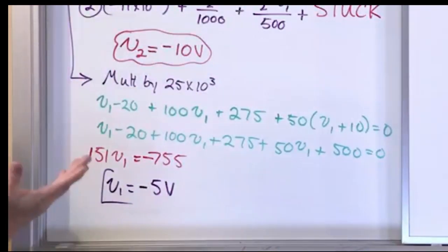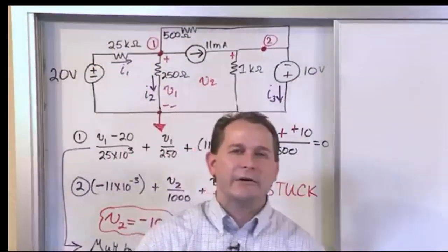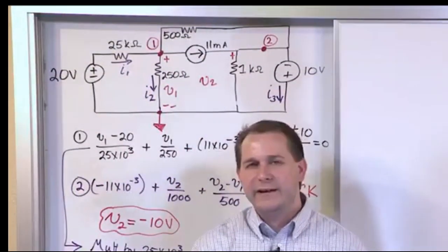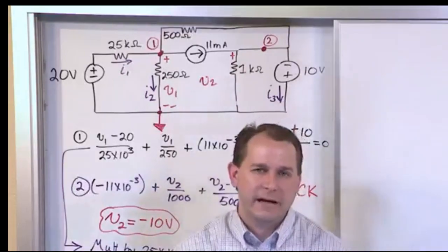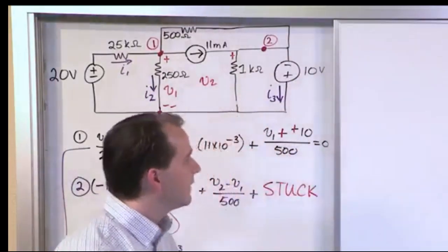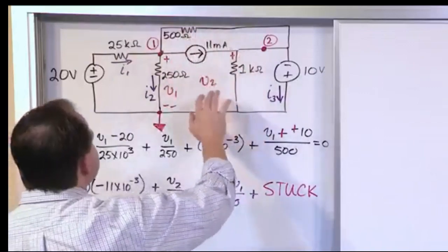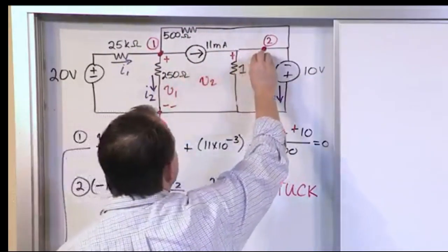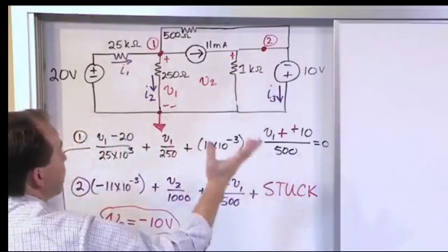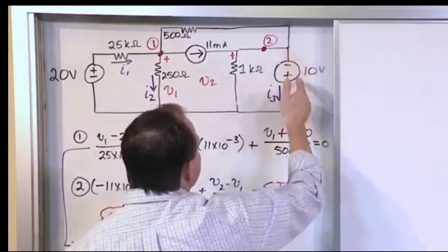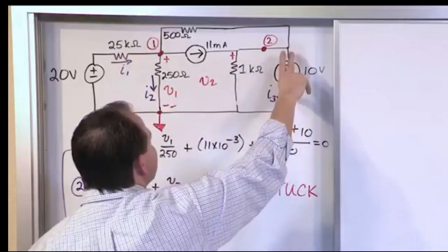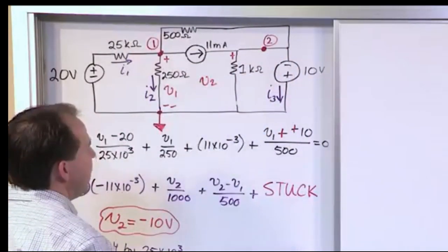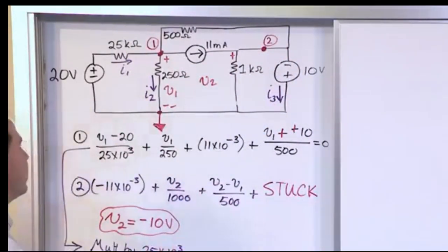So you've solved the node voltage problem. But notice how easy it was. You didn't have to do matrices, you didn't have to do anything, and it's just because of the way this problem is constructed. Physically, the way everything's constructed, to be able to find the currents here, it only involved V1. When you tried to write a node voltage equation here, you couldn't, right? Because you couldn't figure out what the current was in this leg, but then you realized this voltage is equal to the node voltage. And that revelation leads to what's going on.